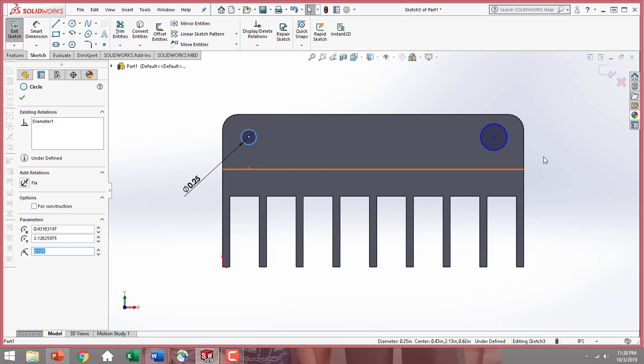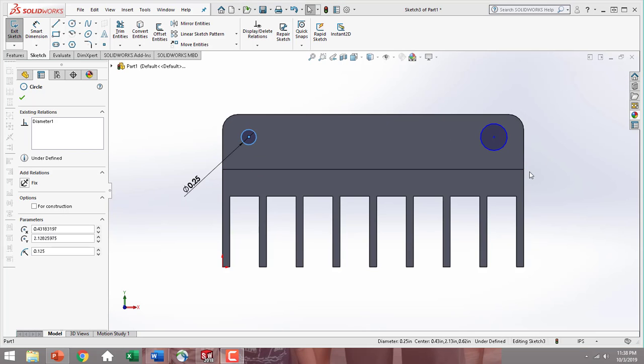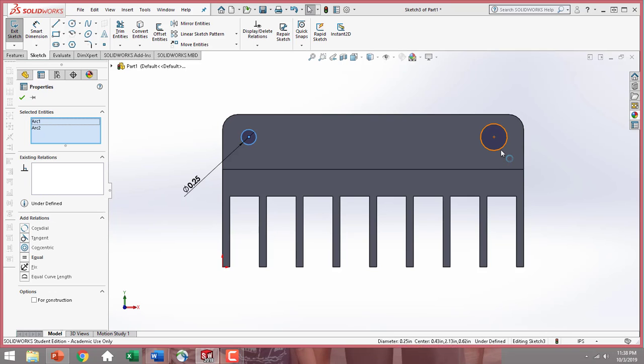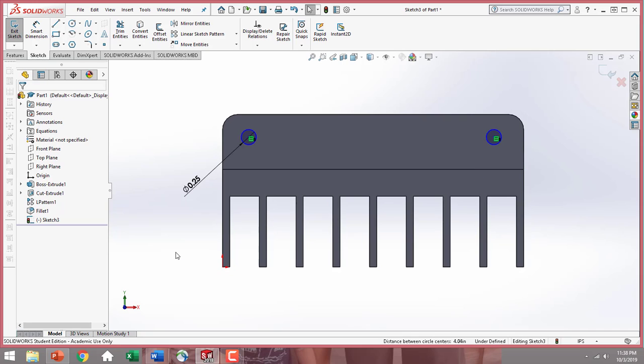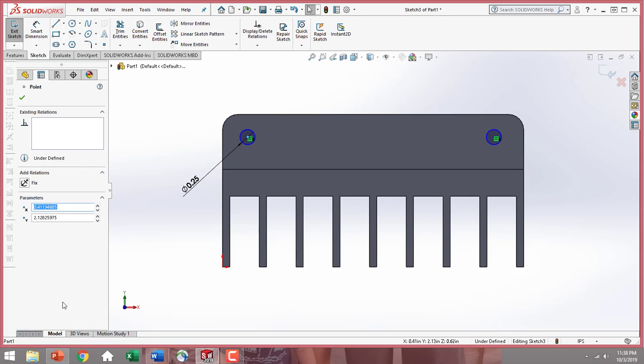I'm going to select its sketch. Go ahead and hit your control key on your keyboard. Select the outside sketch of my second circle, and I'm going to add in the relationship of equals and hit OK. Now I don't have to dimension both of those circles. So I still need a placement for this circle, for both of them actually. Remember, for circle you need its size plus a placement. So since my drawing does not give me a vertical and horizontal placement or values for them, I automatically know that I'm going to need a concentric relationship between this filleted edge and my circle.